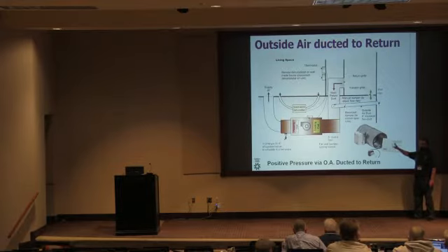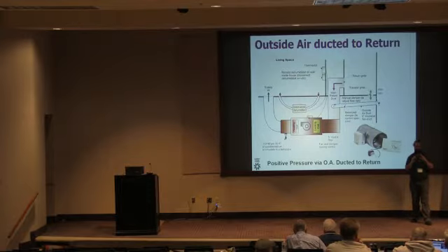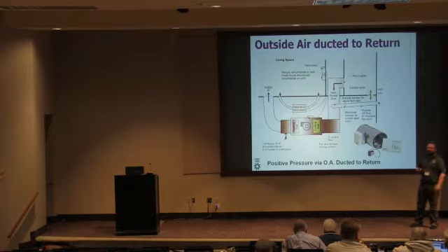And so in order to size it, you do that ASHRAE 62 calculation, and then basically the size of this duct determines your CFM. You basically say, how much runtime do I need to meet the ASHRAE calculation?